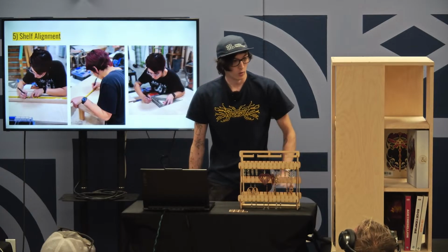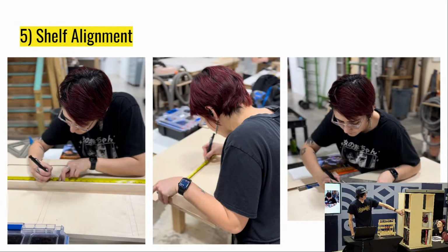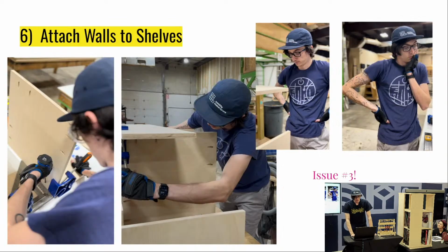Then in order to align the shelves, the assembly for this is kind of awkward because we have to attach the walls to the shelves instead of like building a box and putting shelves into it. So we basically just measured the bottom and top of all of the shelves from the base of each of these walls so that we could clamp and square them up when we were fastening them. Fastening them brings us to issue number 3.